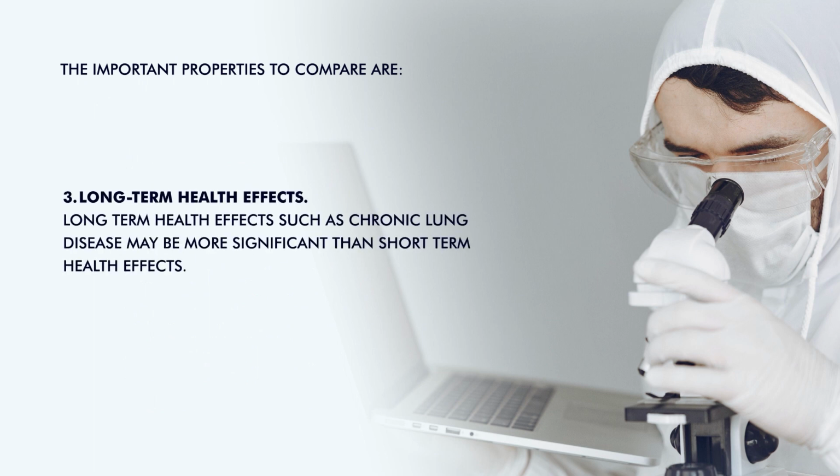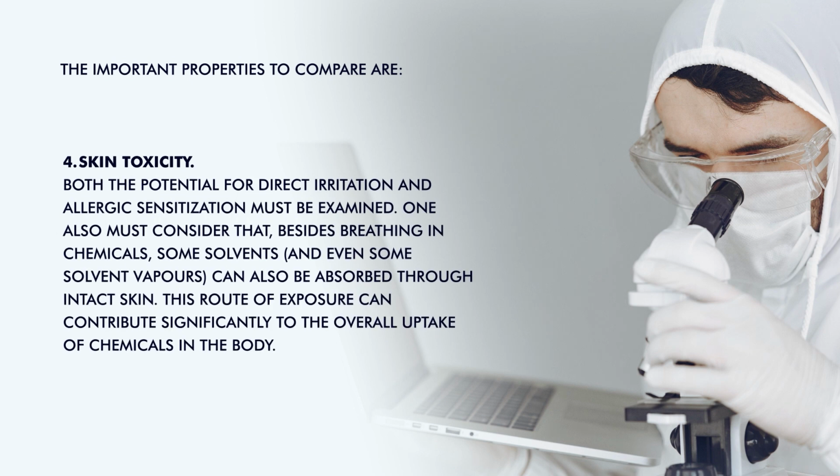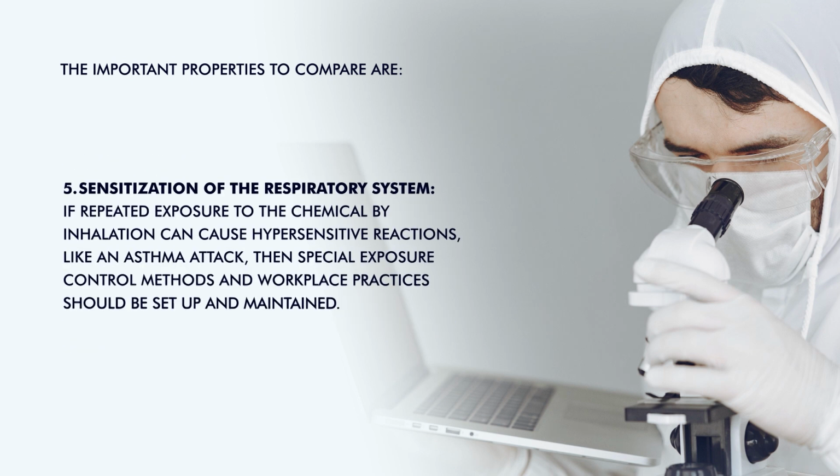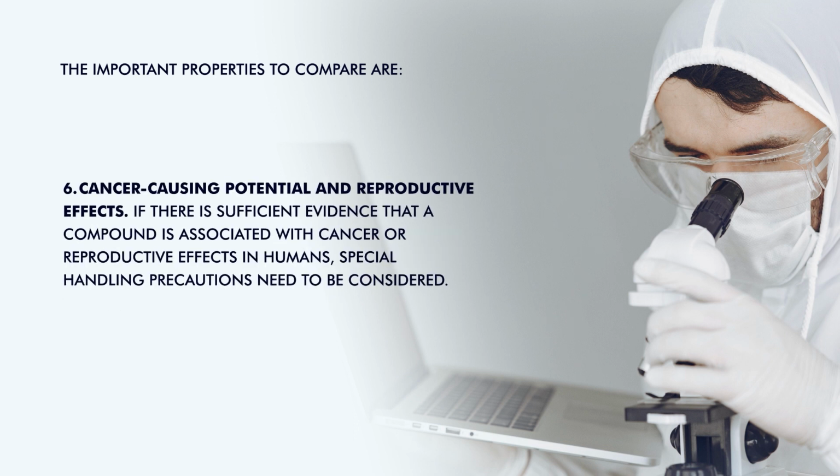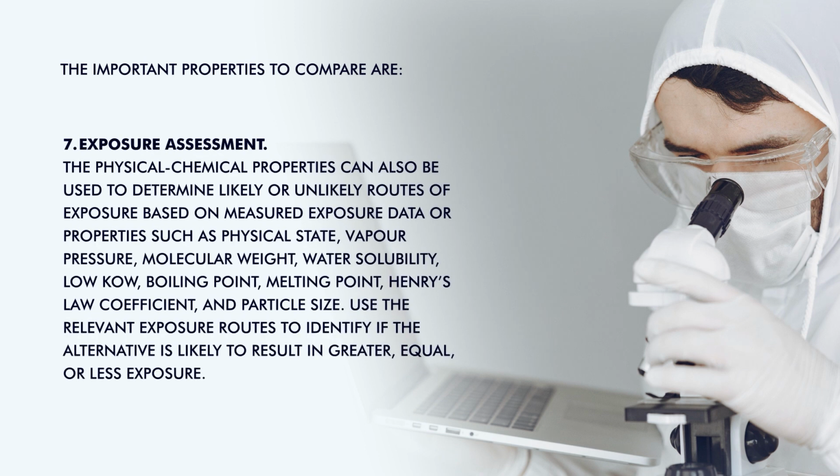Another thing is long-term health effects. Long-term health effects like chronic lung diseases may be more significant than short-term health effects. Skin toxicity is also one of the major things. Sensitization of the respiratory system, cancer-causing potential and reproductive effects are also there for chemical hazards. And exposure assessment is also most important. Physical and chemical properties can be used to determine the likely or unlikely routes of exposure based on the physical state and the particular compound's vapor pressure, molecular weight, water solubility and boiling point, like that.